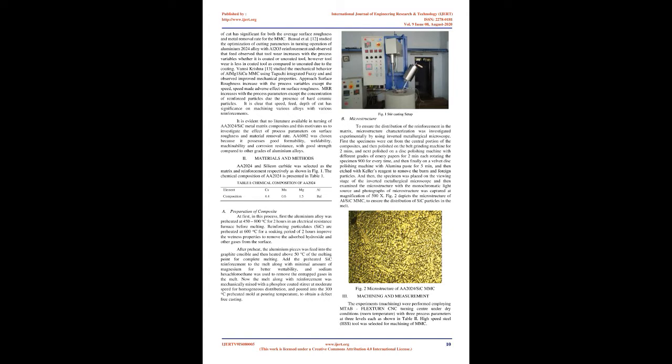Mishra et al. investigated AA7075/SiC metal matrix composites using GRA and concluded that feed was the most significant factor in machining of the composite. Ravinder et al. studied the effect of process parameters on MRR and surface roughness in turning operation on AA7075 hybrid MMCs using response surface methodology and artificial neural networks, and learned that the presence of graphite particles in Al7075 MMC improves the surface roughness. Hybrid composite reinforced with graphite is easier to machine and provided a smooth surface.